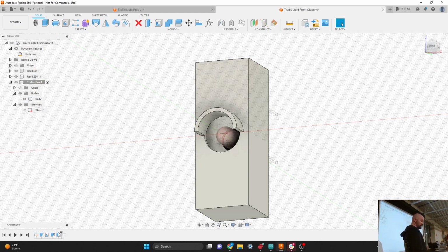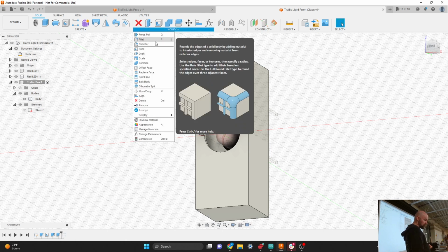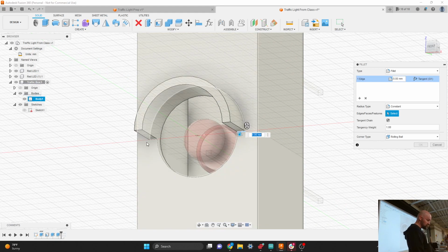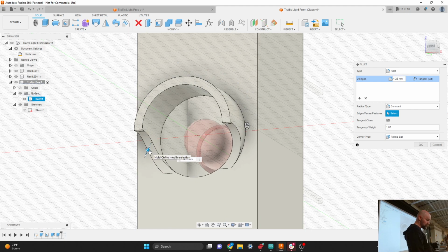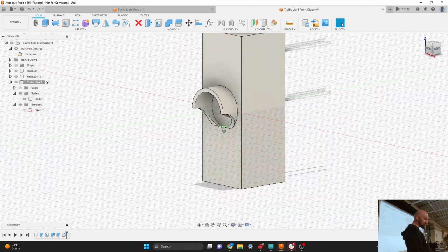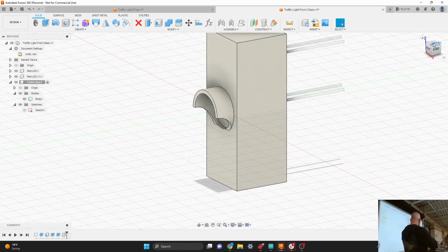But we could add a little fillet underneath these guys, like here and here. This might make it a little bit more 3D printable if we don't have big overhangs. You could print it the right side up instead of having to print it upside down and maybe have some support material waste. You might be able to get away with printing this without support material.